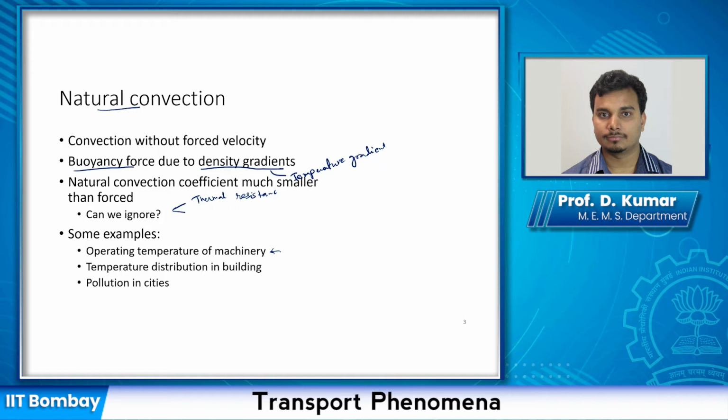The machines could be cooled by water, but very often you rely on natural convection of air for your machines to be cooled. So depending on how much power you can have in the machine, it is limited by how much surface temperature could be maintained due to heat transfer by natural convection.